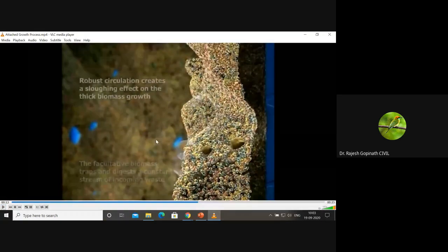Now, over a period of time, what happens? Let's look at this. Over a period of time, this width will enhance. In simple words, these microorganisms will not be able to access the food. They will not be able to access nutrients. They will not be able to access dissolved oxygen. Why? Because there is an additional layer of microorganisms which are more active, more energetic, younger, fresh and new, which is overlying that.